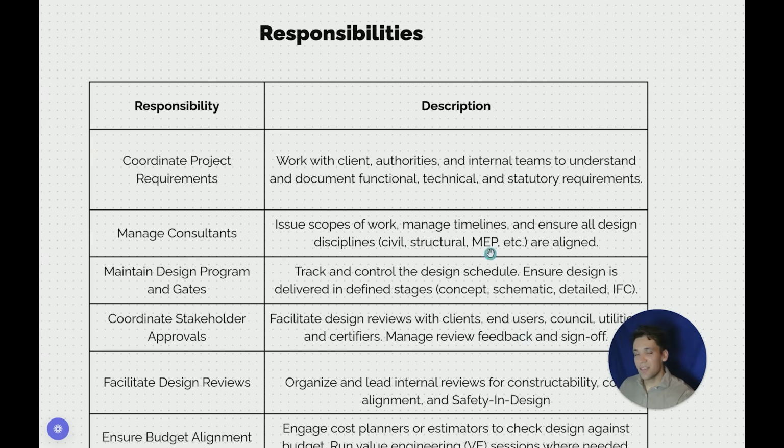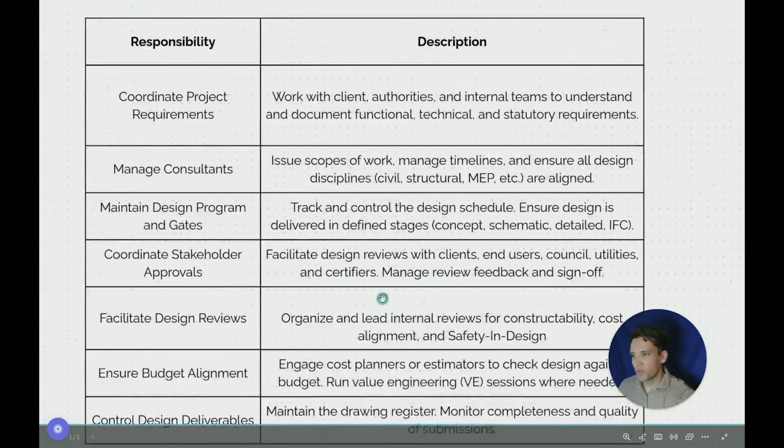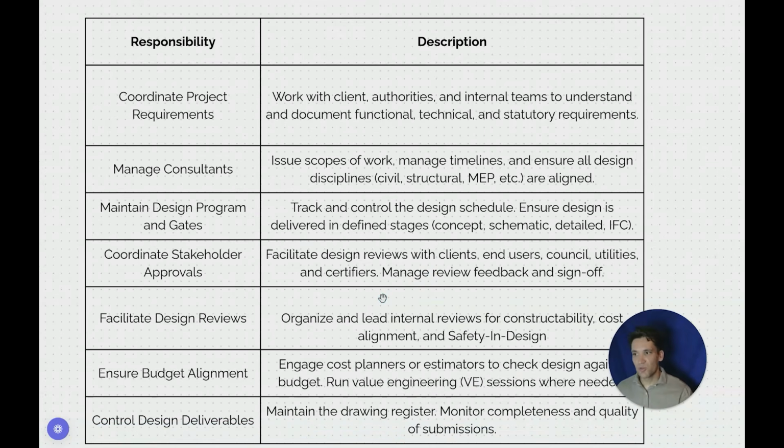On top of that, the design manager is coordinating all of the stakeholder approvals, so they're facilitating the design reviews with the client, end users, councils, utilities, whoever has to sign off the design so it's approved for construction. They're managing the review and coordinating the feedback. So what happens in these design gates is the client, stakeholders will make comments on the design, things they don't like, things they want changed. All these comments need to be closed out before it reaches IFC, and the design manager needs to manage this.